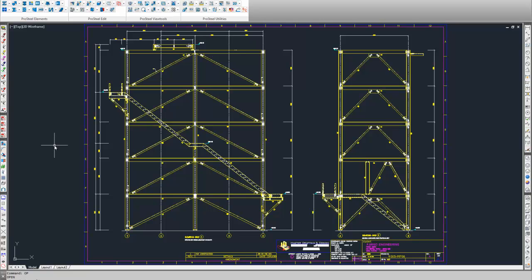Now, the prerequisite for this function to work is that your machine has Adobe Professional installed. So just to be clear, we're not talking about Adobe Acrobat, which is a light viewer. It needs to be the full professional viewer. From there, the creation of all PDFs is very fast. We use the AutoCAD Publish for our batch drawings, such as the single parts and assemblies, and we use the single PDF toolbar for our marking plans and one-off plots.